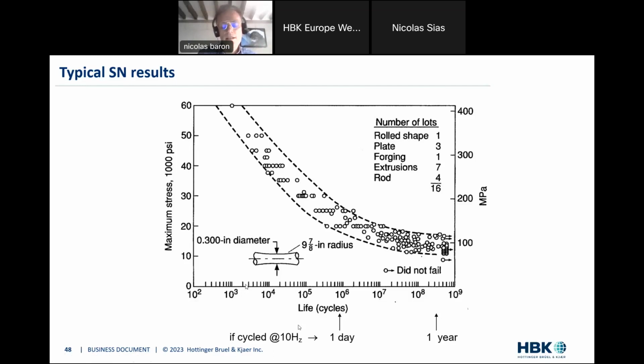Depending on the frequency of this loading, your test might vary from 1 day, if you cycle at 10 hertz, but it could be at a lower loading, it could be that the component will not break until it has been submitted to 1 year of cycling in testing. So it could be very time consuming to have this material characterization.